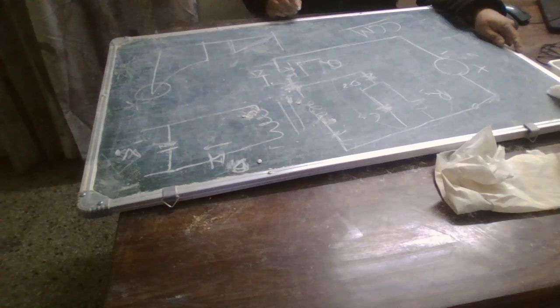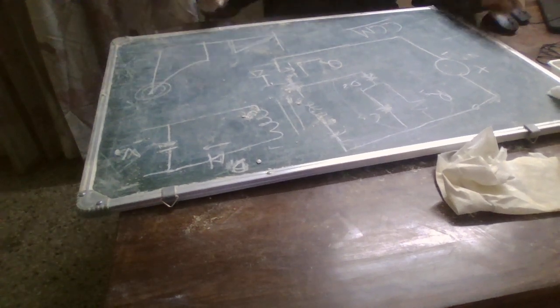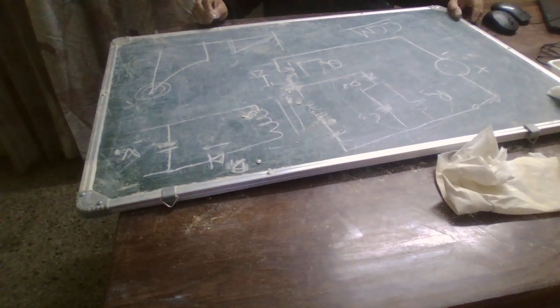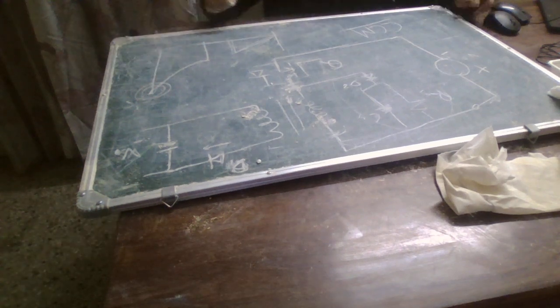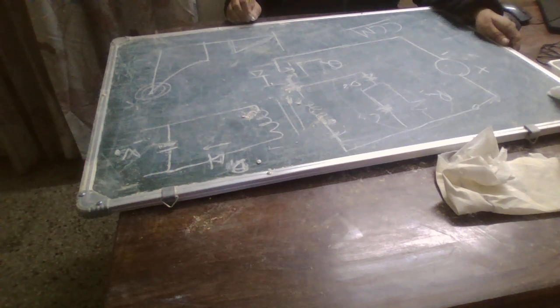One reason the transformer will get saturated is when the change in the flux during the on and the off time are unequal, because otherwise it's going to cause this kind of peak here. That means it's causing a saturation. Now during this continuous conduction mode, the duty cycle is independent of the load, and is basically a constant for a DC input voltage source.